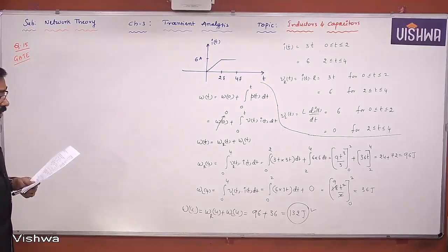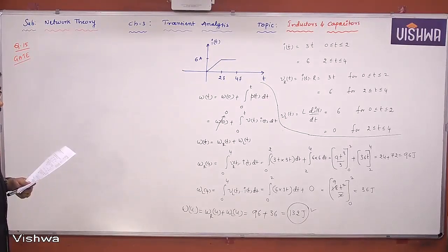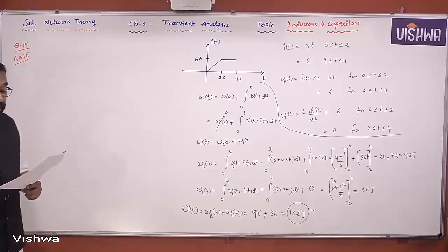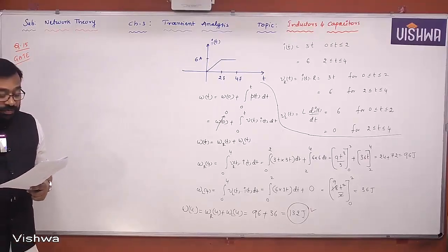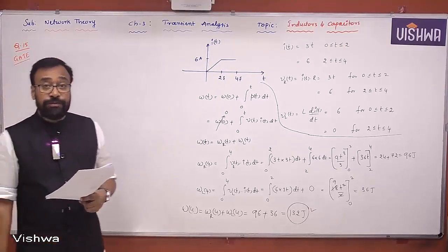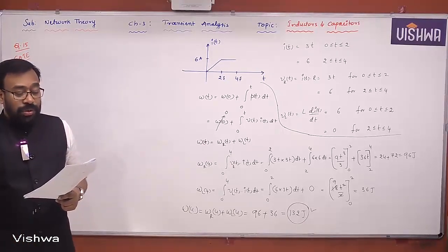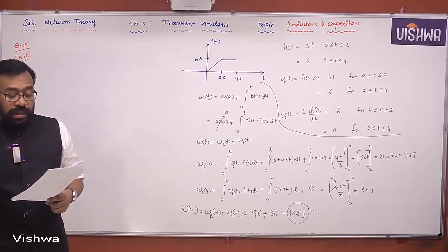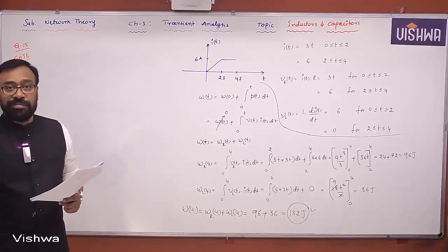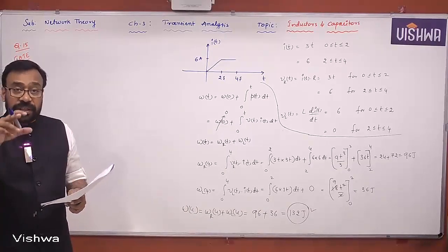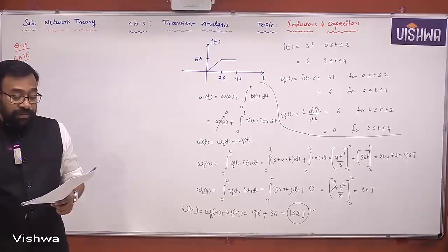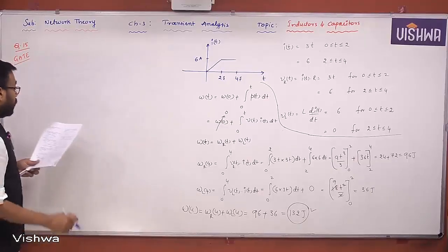When a periodic triangular voltage of peak amplitude 1 volt and frequency of 0.5 hertz is applied to a parallel combination of 1 ohm resistance and 1 farad capacitance, the current through the voltage source has waveform. He has given some 4 options. I think you can observe what kind of waveforms are provided. Let me draw it.